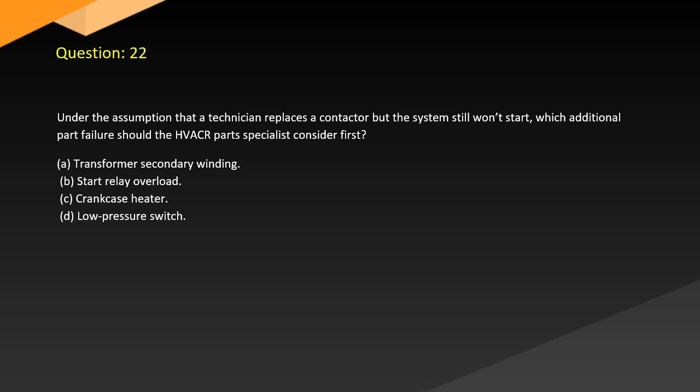Question 22. Under the assumption that a technician replaces a contactor but the system still won't start, which additional part failure should the HVACR parts specialist consider first? A. Transformer secondary winding. B. Start relay overload. C. Crankcase heater. D. Low pressure switch.